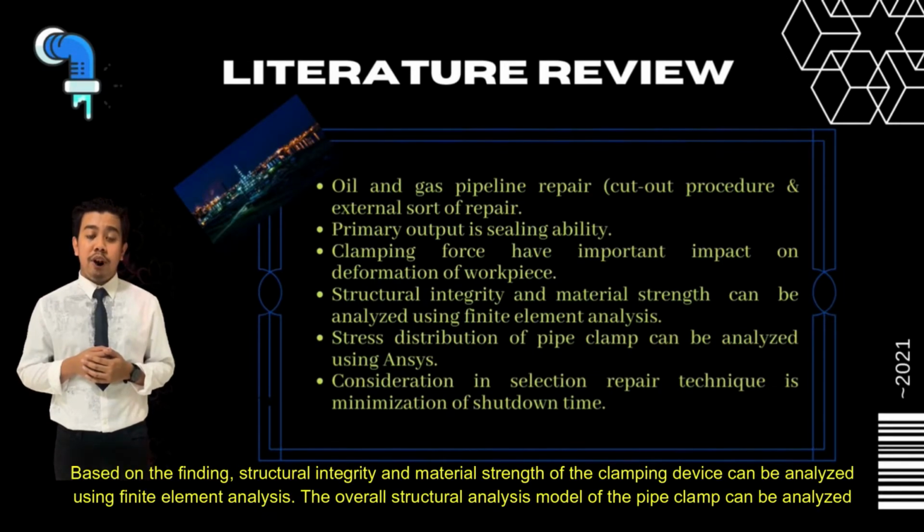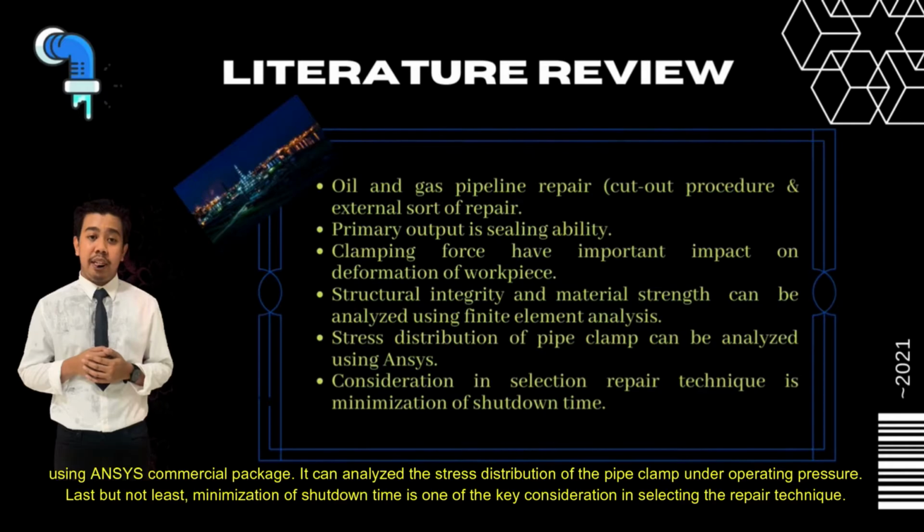Based on the finding, structural integrity and material strength of the clamping device can be analysed using finite element analysis. The overall structural analysis model of the pipe clamp can be analysed using the ANSYS commercial package. It can analyse the stress distribution of the pipe clamp under operating pressure. Last but not least, minimization of shutdown time is one of the key considerations in selecting the repair technique.